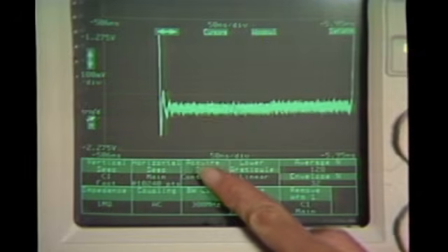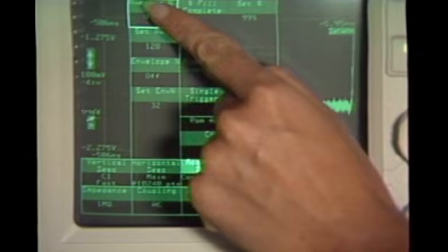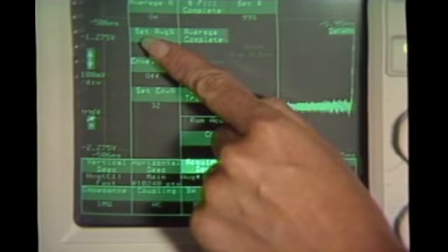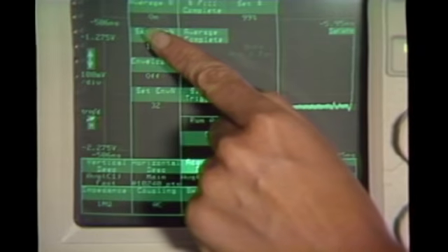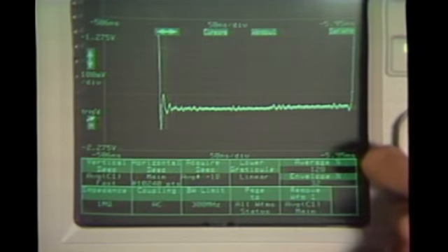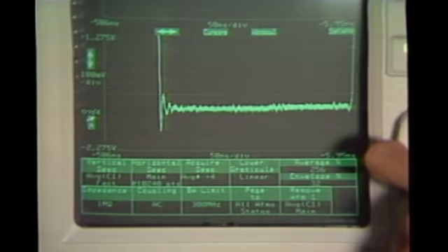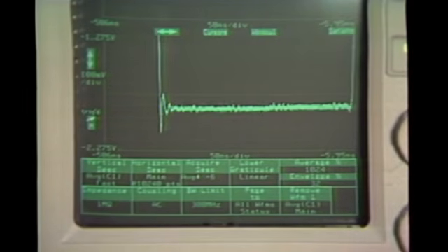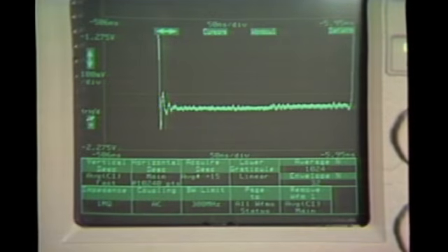Random noise can be eliminated by taking the difference between the time reference sample points and the random noise. During each acquisition cycle, the scope adds a correction factor based on averages of previous acquisition cycles. The result is a cleaner, more precise representation of the signal.